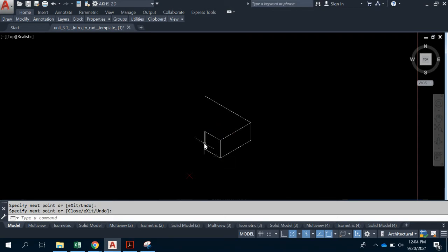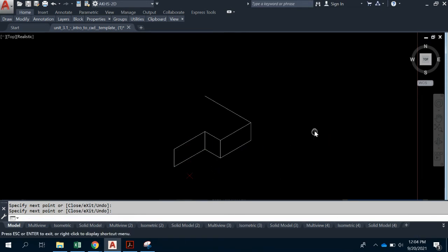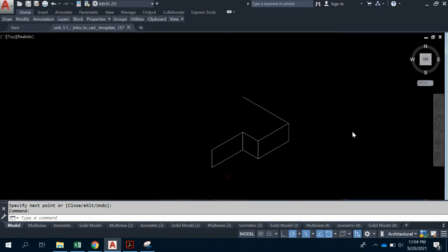Okay, then we want to come this direction and add that other side profile. We're going to go from these two corners and come down into the left, and start here and go down into the left. This distance should be 1. Coming down 0.5, or let it snap. Either one will work, maybe. Okay, so that one's not snapping, which is fine. So I'm going to type in 0.5, and then I'm going to bring it back to that corner right there. Okay, feel free to pause the video or rewatch any of this if I'm going too fast.